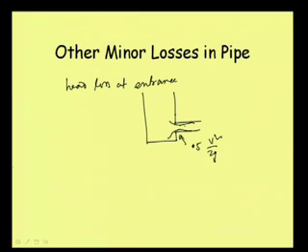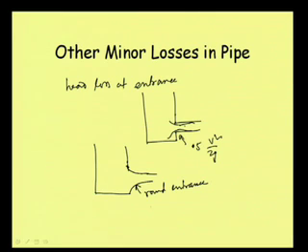Well, these are fine, but if we think that we need to reduce this head loss, then where we have the entry point, we need to make a rounding of this pipe. If we can have our connection in this form, then our head loss will be minimum. There will be some head loss, but it will be less if we can round it off. So, with a round entrance the head loss will be less, and if possible, we should make our entry point in this form.